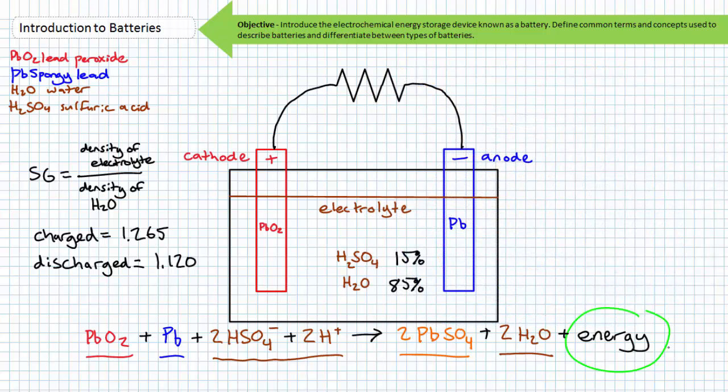If there was a marked differential between one of the cells, one might suspect the inordinately low cell is being damaged. Given a battery is a series arrangement of cells, one can use basic series properties to determine the effect of a damaged cell. Voltage is additive in a series aiding arrangement, and current through elements in series is the same. A damaged cell with no voltage across it will reduce the battery's voltage by that amount. A damaged cell not permitting current through it will effectively cut off current produced by the whole battery. In this case, though, all 3 cells read close to the same low value, and we can rest assured that this battery is uniformly discharged.